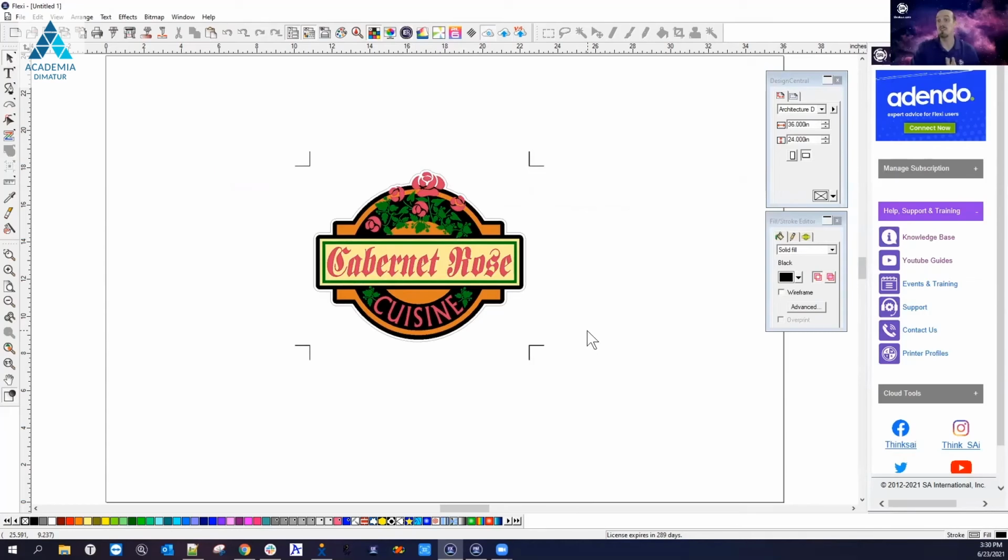Now, let's just say you're exporting it to your own PC and you're going to send it to RIP via Raster Link or Onyx or something, and then you're going to bring it back to Flexi. Then you could just click one of these buttons, send it over, and you're good to go. If you are outsourcing it and sending it somewhere else, then you can just hit File Export. Export this as a PDF or an EPS or an AI file, whatever file they need in order for this to work, and they print it. The job comes back to you, so now you have the print job.